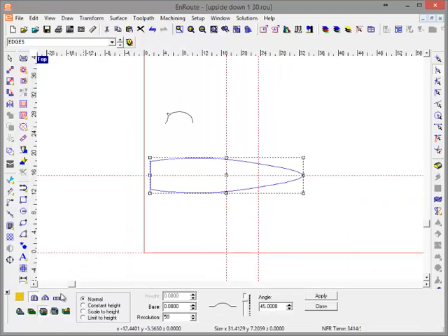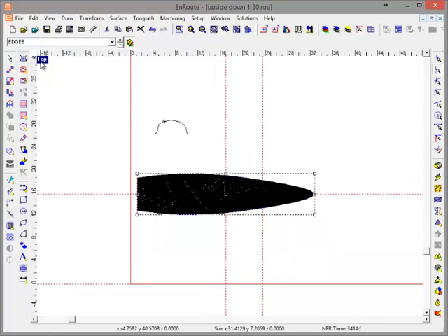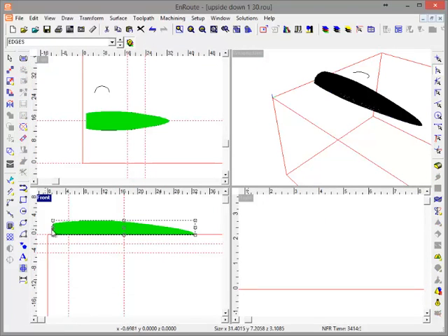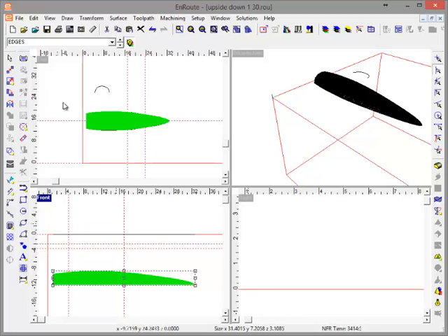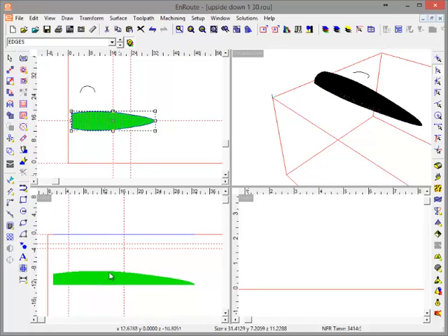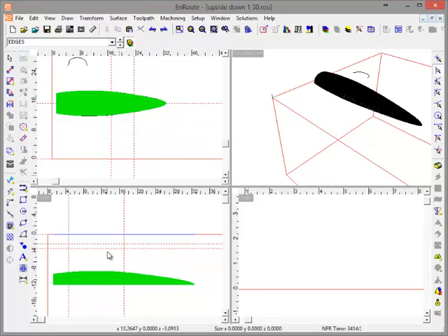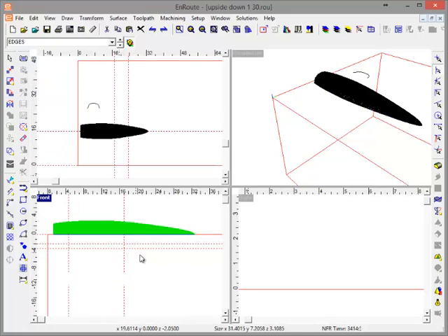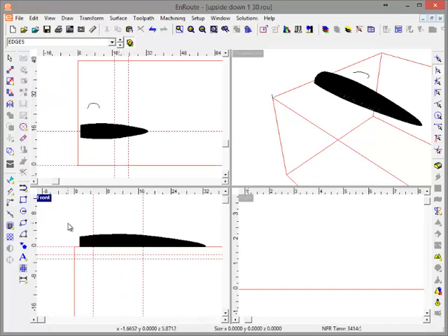So I'm going to do a flat, no thickness relief. I'll probably bump this up to 100. And now I'm going to say, show me the other layer. And I can see that my relief, my mesh is sitting right on top of 0 and right where it needs to be applied. If for some reason it was down here, it would look the same from the top view, but nothing's going to happen here. You have to have your mesh object relative to your relief so that when you add it, it's going to add what's above your relief base foundation.